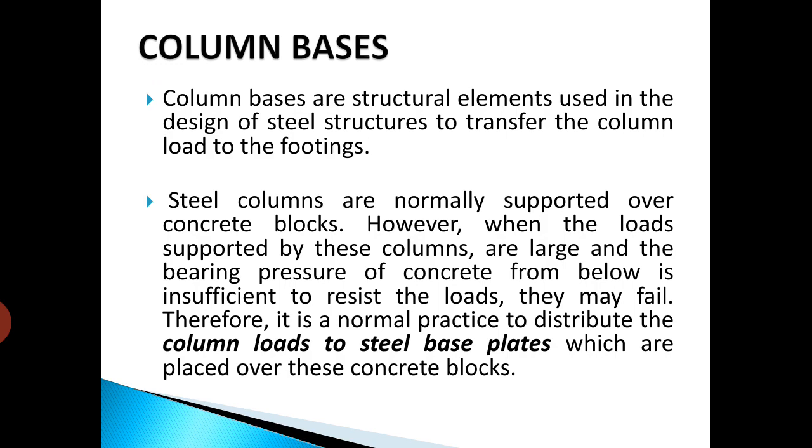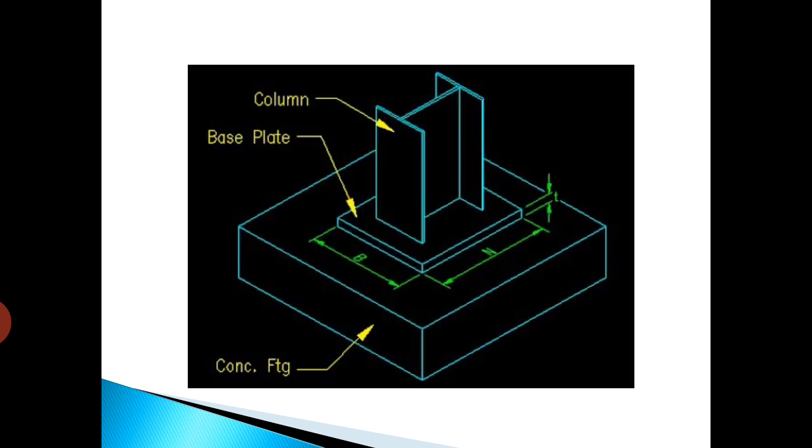To overcome that, in steel structure, at the end of the column, a base plate is provided to distribute the load safely to the pedestal and from the pedestal to the soil.